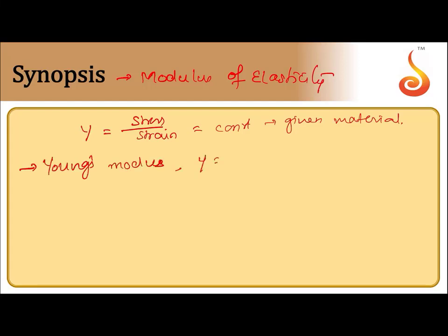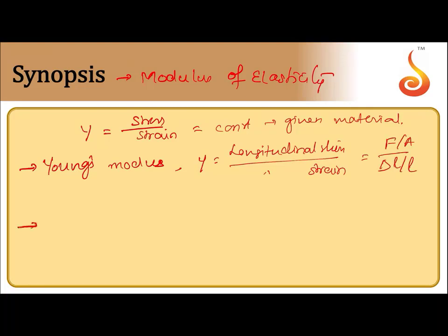Which is tensile stress or longitudinal stress divided by longitudinal strain. We can write it like this: F divided by A divided by delta L divided by L. Second is bulk modulus of elasticity,